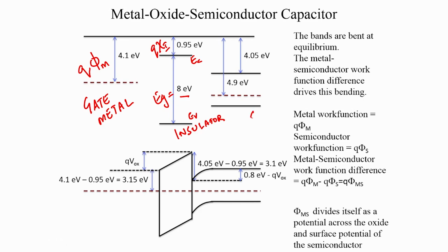And then finally, you have your semiconductor. Okay. So, we have not yet created the junction in this diagram. So, we have the semiconductor, and here you have some band gap. So, for example, let us say the band gap is about, if you take silicon, it is about 1.12 electron volt. Okay, we have some band gap, and the semiconductor is doped p type, which means that the Fermi level of the semiconductor lies a little below mid gap.